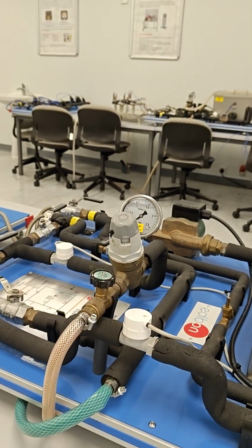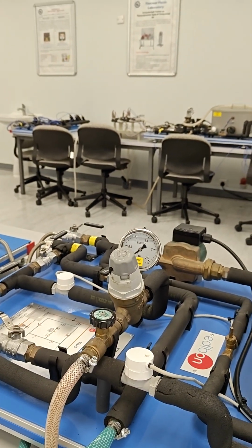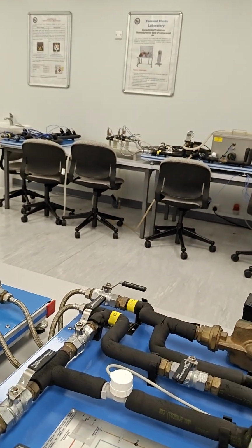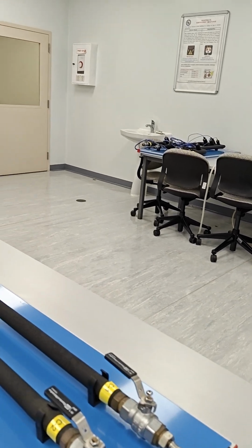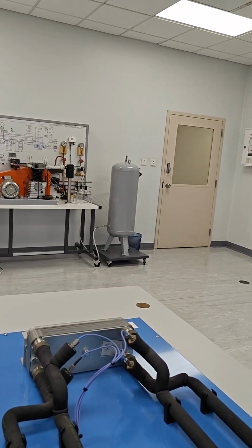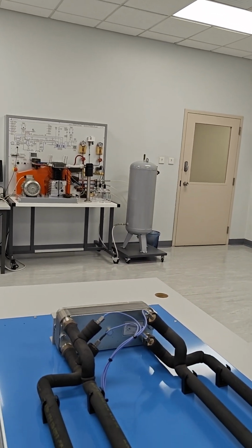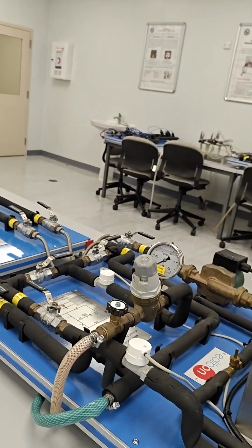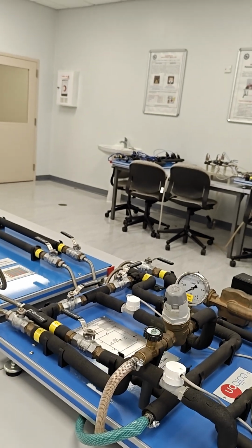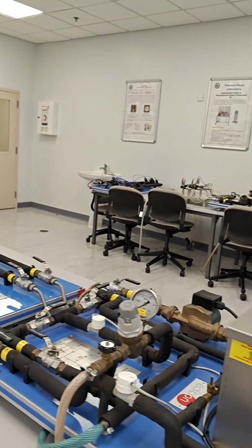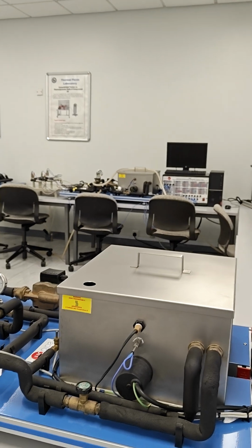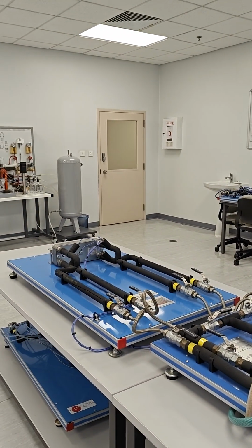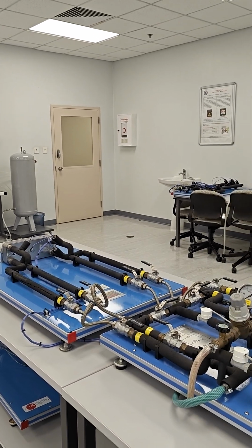Then new water comes in at the room temperature, basically like 20 degrees or 25 degrees, enters the system and then goes again through the valves, through the pipeline into the heat exchanger, exchanges heat with the hot fluid, and then it comes out hotter and exits the system through the green pipe into the ocean. So this is the loop for the cold fluid. We have two loops, hot water loop and the cold water loop, going into the heat exchanger, exchanging heat, and then again the process repeats itself.